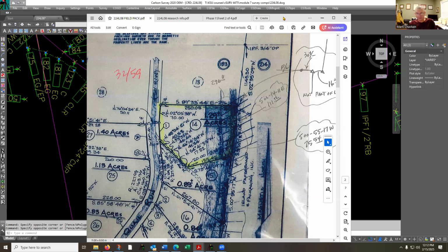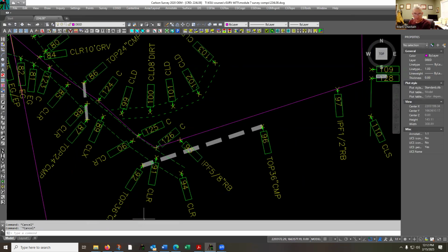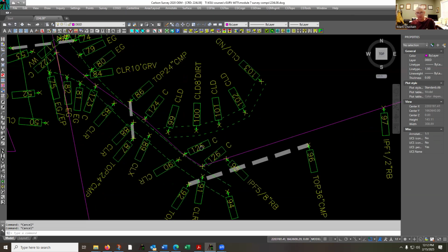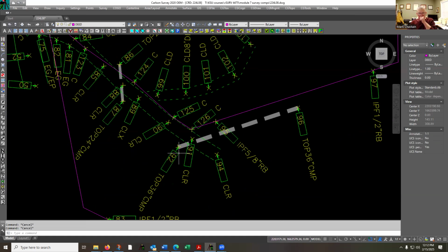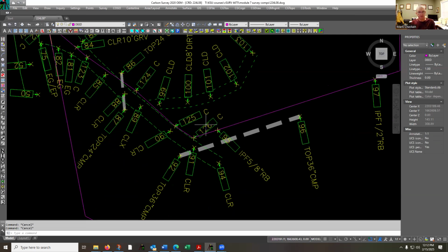Or if the surveyor incorrectly or in error located a driveway in the wrong place, maybe a bad backside, who knows, then that would not control. But we have monumentation. We have 95 and 97, which nail us down nice. I mean, we know that 95 and 97 fit everything in. And notice we start out in the center of the driveway. Then the property line eases up to the north. Maybe these folks wanted to pull the driveway, excuse me, down on their property. Maybe on the original subdivision plat, it was just a logging road or some sort of bulldozer trail.